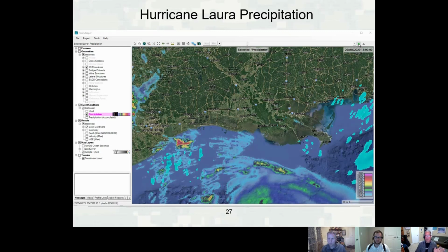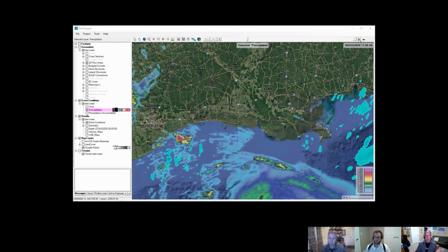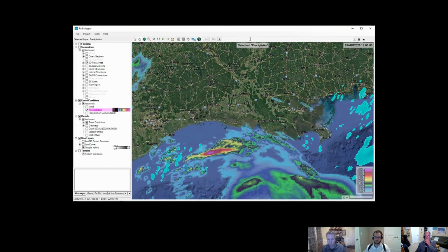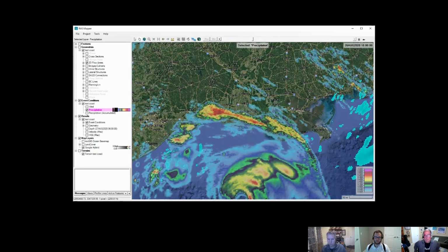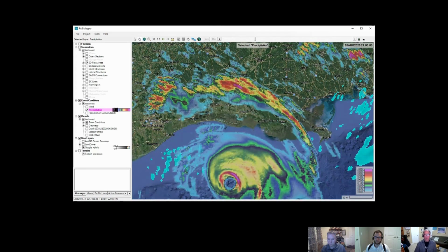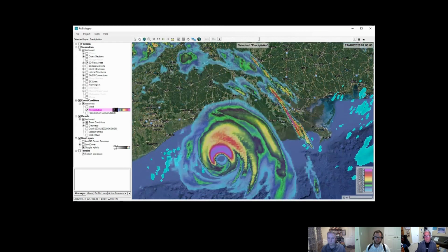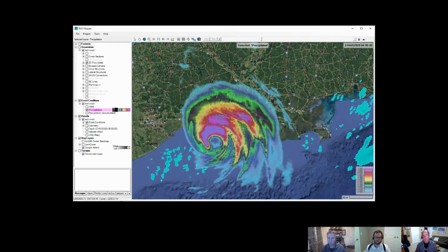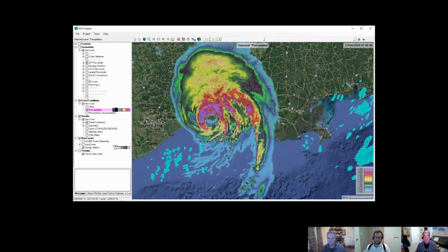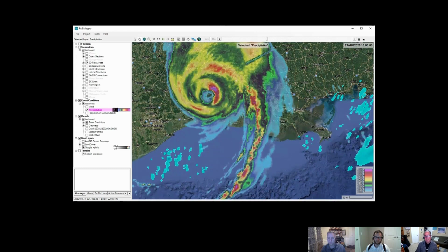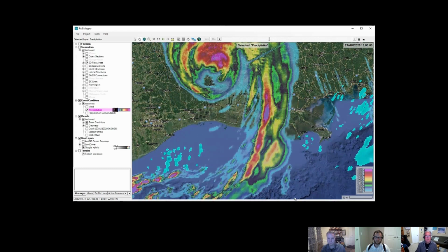The first thing is going to be the precipitation that we modeled and had brought into RAS. So here's a little animation of the precip. Darker colors are more intense precipitation. And here comes the hurricane. You can see the eye of the hurricane, but this isn't wind. This is just showing the precip that's falling. So that's an input source into this model in RAS.